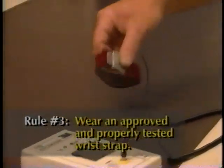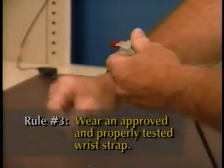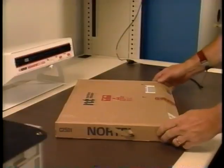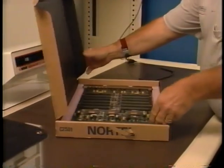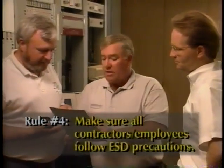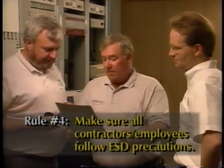Rule number 3, wear an approved wrist strap that has been properly tested each day prior to use before opening a circuit pack container. And rule number 4, make sure that all contractors and other employees follow our first 3 rules. If these rules sound familiar, they should. They're contained in this electrostatic discharge job aid. Here's an overview of our job aid along with more tips on avoiding ESD.